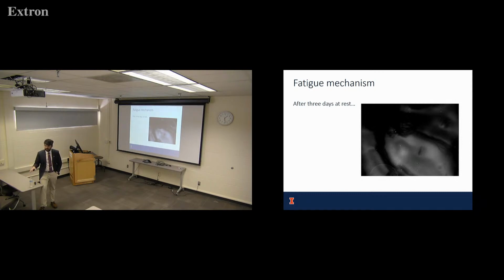What is the difference between those? At least we had a hard time characterizing the difference between plastic deformation and nonlinear. Damage is easier because you see it physically. But actually what we found is that you can heal damage in asphalt binder, right? With heat or those kinds of things, you can heal damage, it will flow. In this case, we didn't apply any heat, but we did see those cavities start to change.